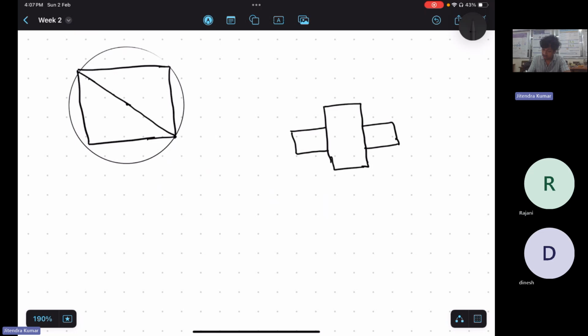Now, whatever the circle area would have been required, that is optimized in this fashion. I'm bad at drawing, but you understand that compared to the entire area of the rectangle, you now have a reduction in the area of the circle. That is what is called core stacking, or rather a stepped core.